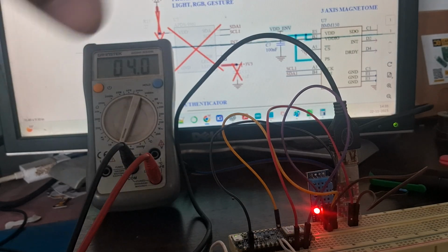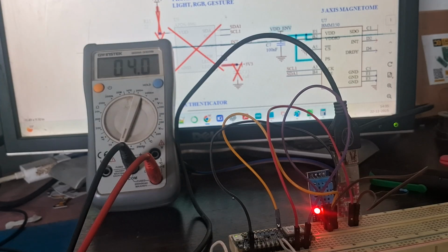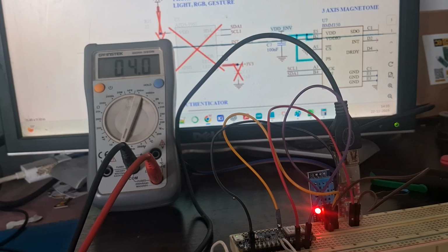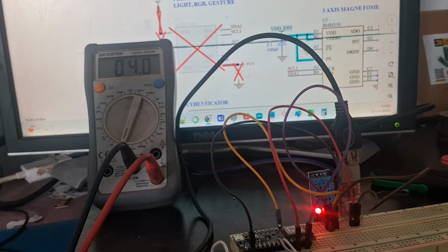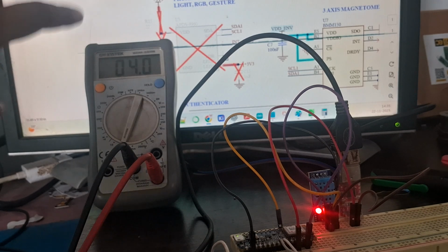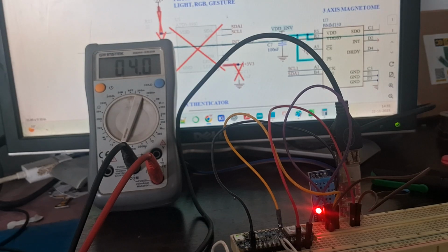Okay, so now the Arduino Nano BLE is in advertising mode. The current consumed during this particular mode is 4 milliamps. In our blog, embeddedDesignblog.blogspot.com, we did a detailed power calculation of how much current is distributed among the different peripherals of the Arduino Nano, and how this 4 milliamps is divided between the peripherals.